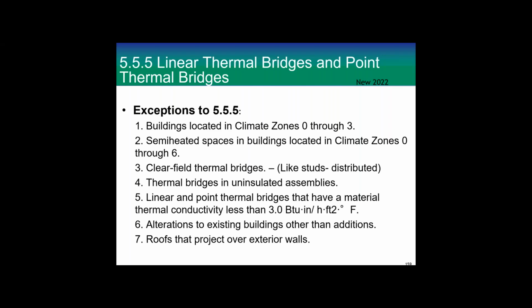So I'll multiply the area times the U value times 22. You can see that 22 is a lot less than 68, and so we couldn't get payback in climate zones 1 through 3, with cooling dominated climates where the delta Ts aren't so big.